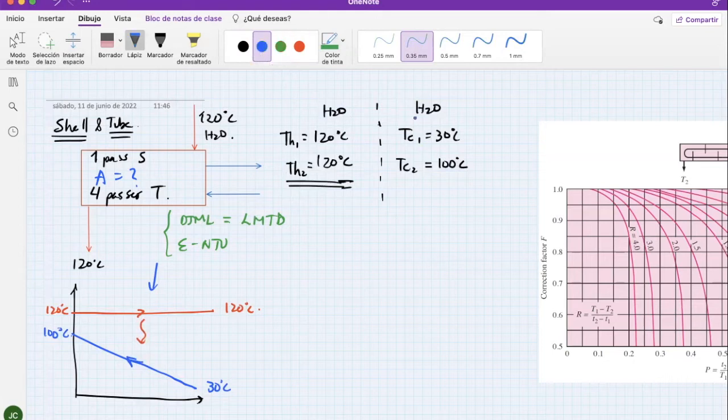Okay, so here I go, guys. For this cold water, I have that the C is 4.184 kilojoules per kilogram Kelvin. For this one, this doesn't have a heat capacity. I will explain why, and this explanation will lead us to a simplification of how to solve this type of problem. You will say, well, it's H2O, it should have the same value. But this thing is changing phase. Whenever you're changing phase, heat capacity becomes senseless. It doesn't have any meaning when you are changing phase, and I will let you know why.